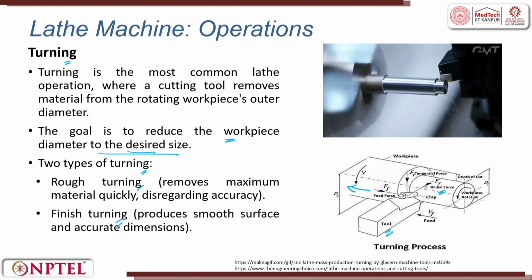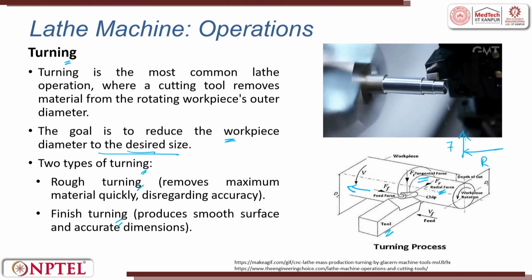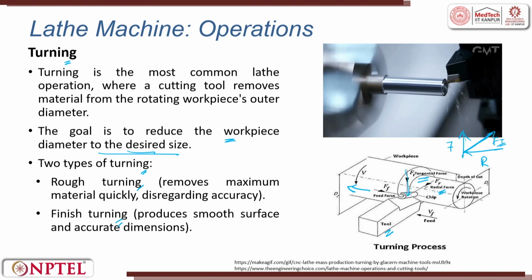And a resolution of these two at an angle of 45 degrees is the tangential force. So this is the radial force, this is the feed force. The tangent of it is Ft, which is the cutting force. So that is the tangential force. The tangential force also tries to move the workpiece down. The tangential force is otherwise called the cutting force.